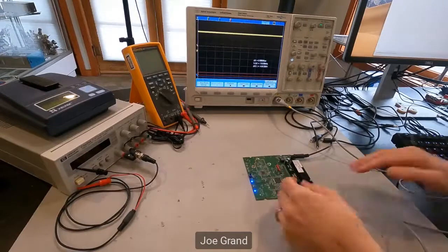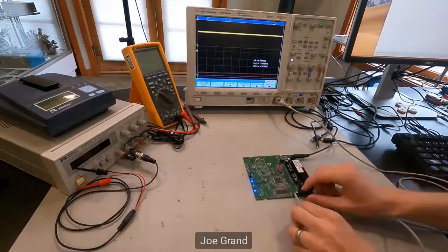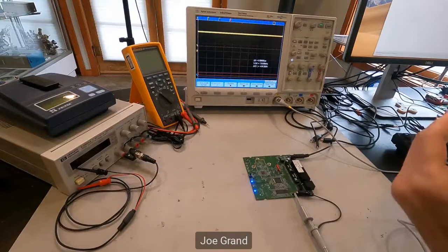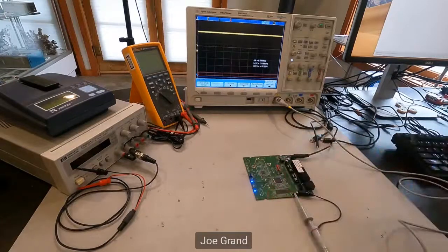Now, knowing that, especially in our case, we know there's a UART interface here. UART, again, is an asynchronous serial communication interface, very, very common because it's generally going to be a point-to-point type of system, and it's usually an interface that a target board will use to transmit information to a human, and a human will use to communicate back to a target board.